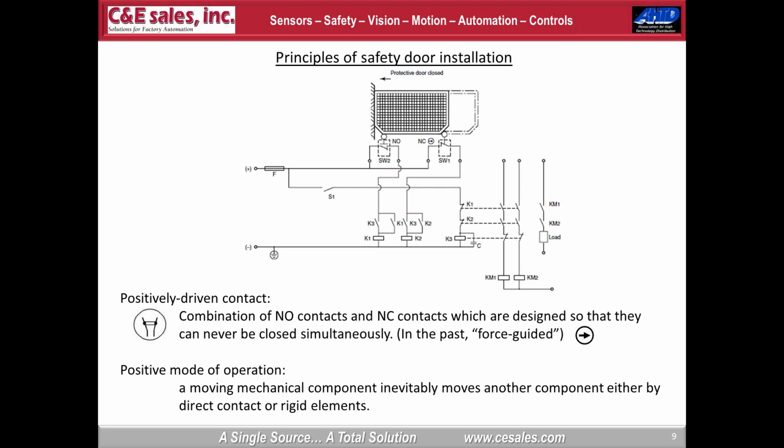And what that means is that in a device that has both normally open and normally closed contacts, the switch or the relay is constructed in such a way that those two types of contacts can never be closed at the same time. That's what it means. It keeps a certain minimum gap in there should it fault.